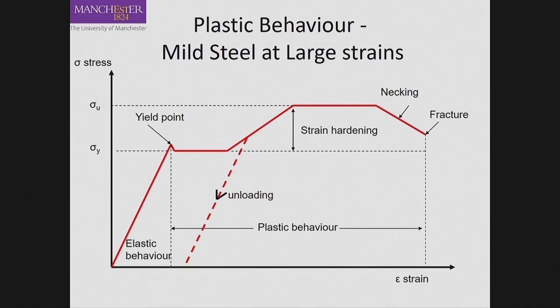So take a metal paper clip, bend it. Unfortunately, this is plastic, so I couldn't demonstrate it very well. Take a metal paper clip, bend it one way so that a permanent deformation forms, and then try to make it straight. You will invariably come up with two kinks in the opposite direction next to each other. So it will be almost impossible to make the initial bend a straight one because of this property of strain hardening, which he mentioned just now.